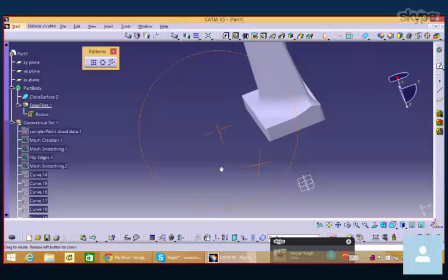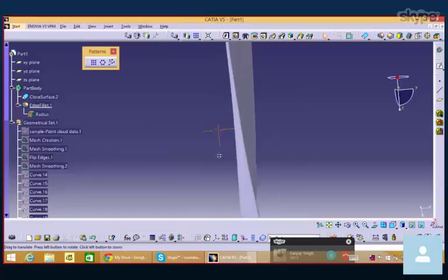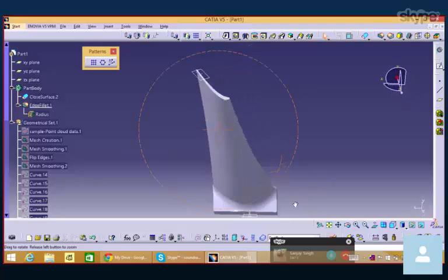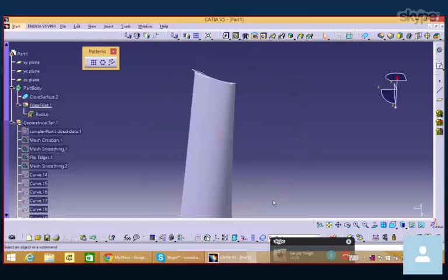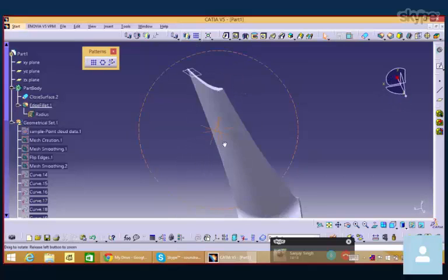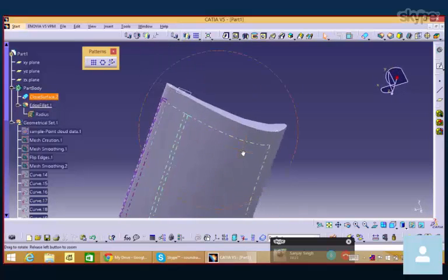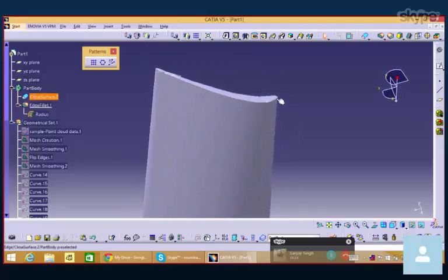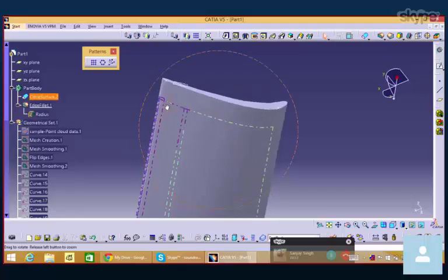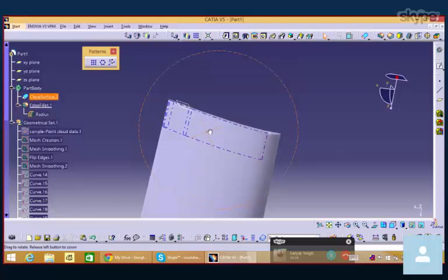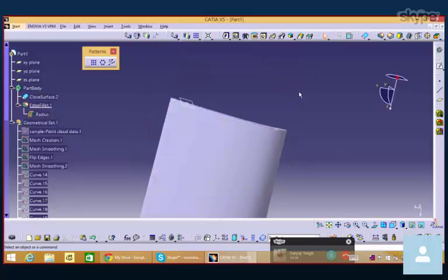But due to that surface creation, I mean the top. How did you do that here? I forget. How did you trim it? No, I didn't trim it. I just placed it approximately over here. So if we create a 3 point plane, you see the plane is not flat, so I should create the plane flat. It will create a flat surface. We can give up to limit while extrapolating.